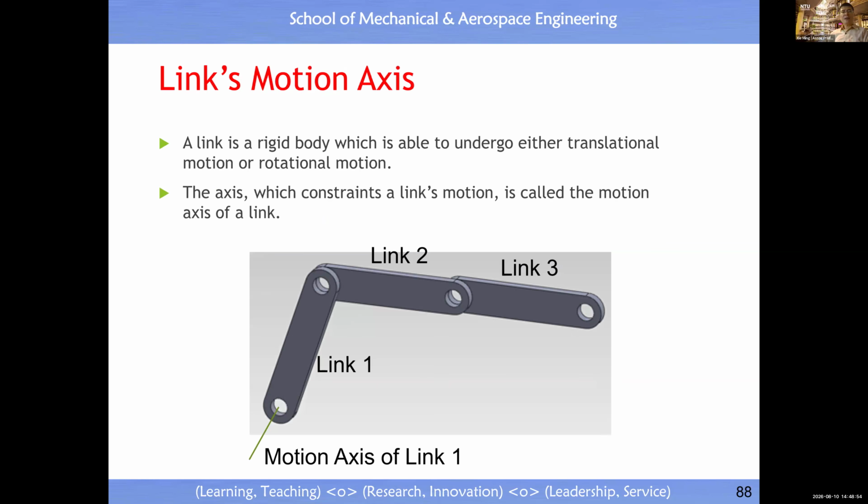Okay, clear? The third convention is how to name and label the motion axis. The convention in robotics is to name it the z-axis. You cannot just name it the x-axis or y-axis, or you get it all wrong. So the motion axis is the z-axis. Then what we have left are the x-axis and the y-axis.